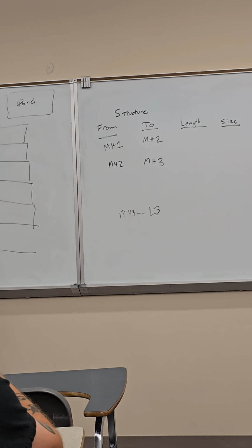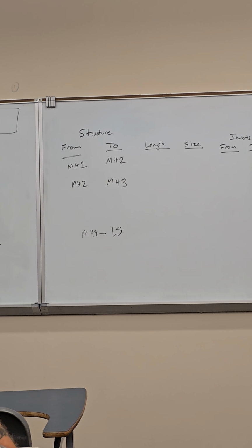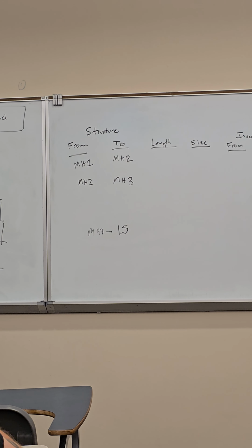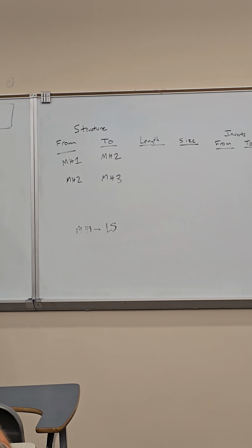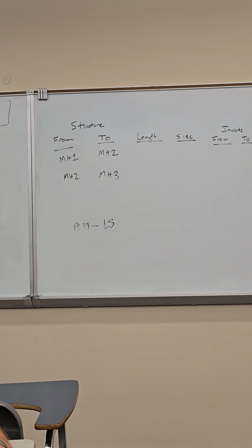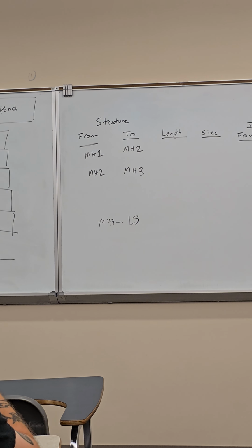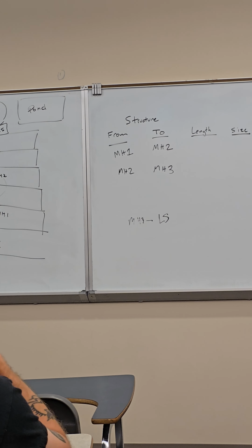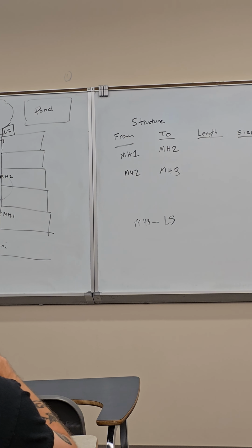Yeah, what was the slope standard? It's in the PowerPoint. Okay. So there's a minimum. Okay. So just use the minimum? That's up to you. You can't go any flatter than that. Okay. And think about, why do we have a minimum slope? So that it keeps flowing. Last thing we want is that not flowing, right? You gotta keep going. So you want a minimum slope so it flows.